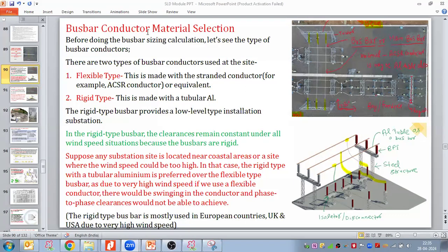In my last substation, it was 220 kV, and in the main bus, we are using PT for voltage. Yeah, there is no problem in that, Partha. You can use the PT, no harm at all. Even PT is better compared to the CVT, the error is lower in the PT compared to CVT.